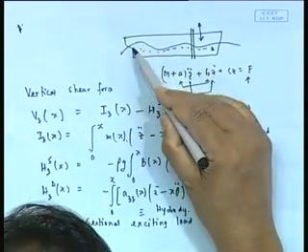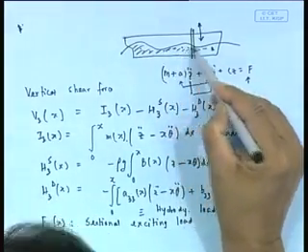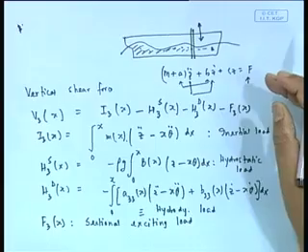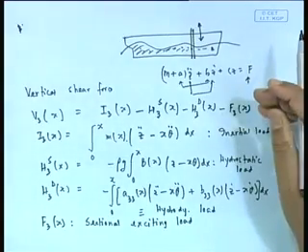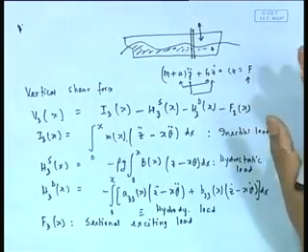See, I have this ship underwater, this part, right? Now, what did you do earlier in finding out, let's say, the shear force and bending moment, wave induced? You simply considered a profile, a trochoidal profile or something. From one side, simply took the load, sectional load, to be as what? Rho g B, weight minus buoyancy. That's all that you have taken, right?